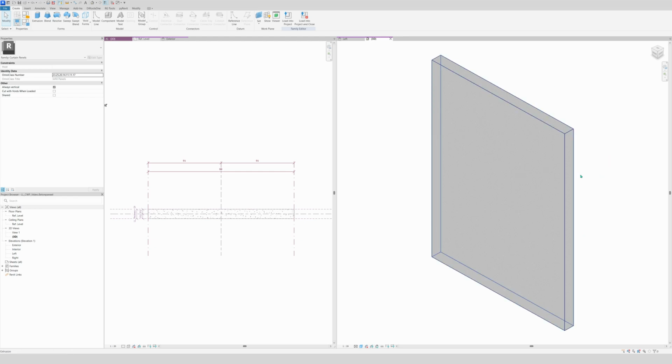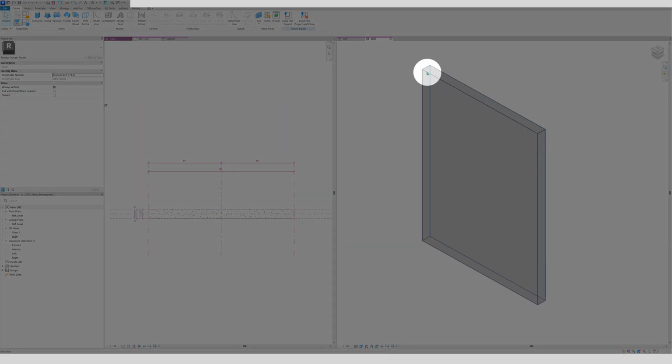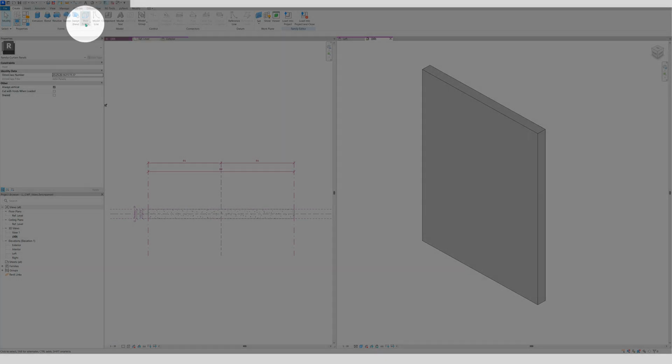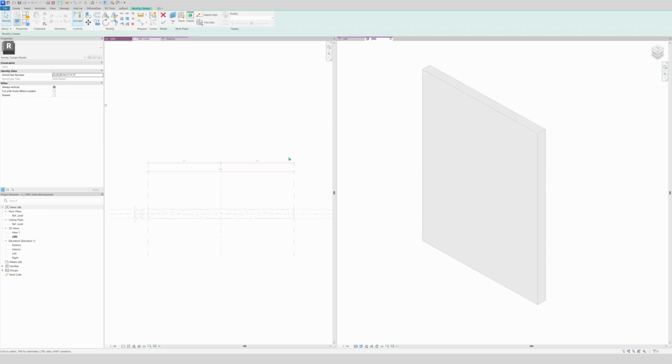As you see, voila, very better, and the concrete pattern. Let's go. So first of all, we click on our 3D model, and now we're gonna make the chamfer right here on this contour of the concrete panel. Well, first we start with void forms, and we will use a void sweep. So select void sweep, and now it says to select or sketch